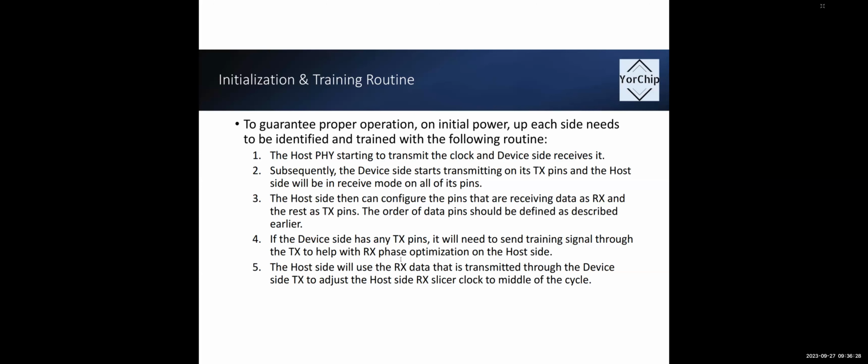1 to 2 gigabits per second. Sorry, wait, 1 to 2 gig clock rate or 1 to 2 gig? I mean, it's still going to be DDR in gigabits per second, right? Now, I do think there's a valid question of whether you actually want to be DDR or SDR. I think we want to be DDR.